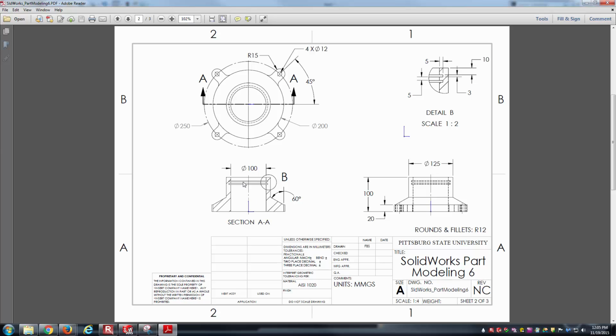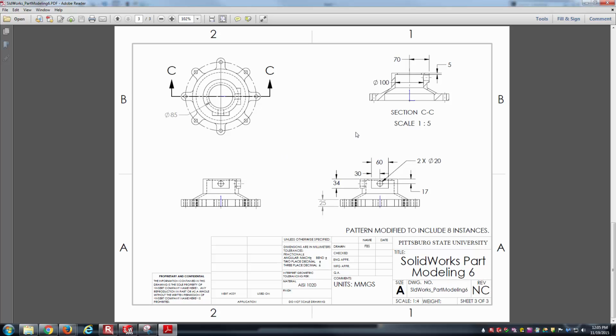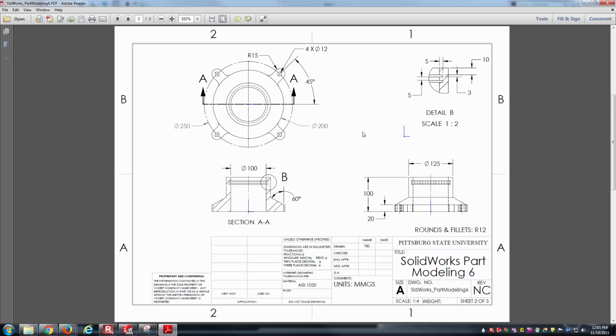And so one thing about the interior region of this part here, you've got the hole with the snap ring grooves, and notice in the second version of the part, that's a totally different piece of geometry in here. And so the way I'm going to approach that is that I'll first go ahead and create a revolve feature in order to create most of the material. And then for the initial instance, I'm going to create a second revolve cut feature to create the hole and the snap ring grooves. And then that'll allow me, when I go to configuration A, to suppress that revolve cut in order to put in the new geometry on the interior of the part there.